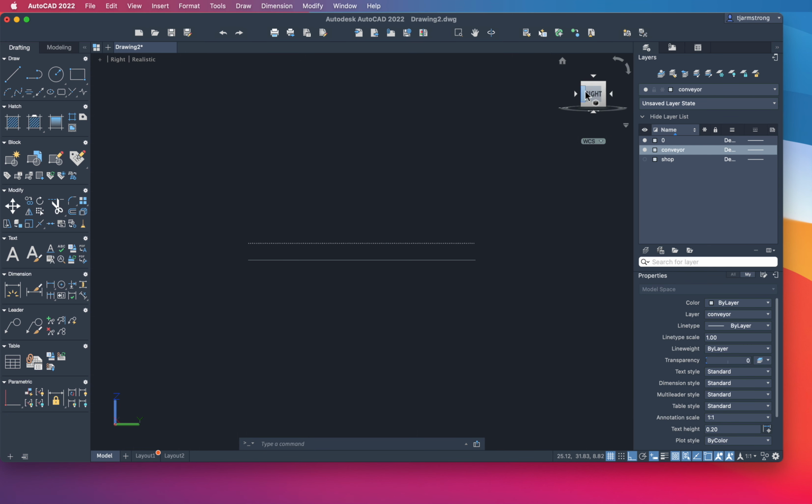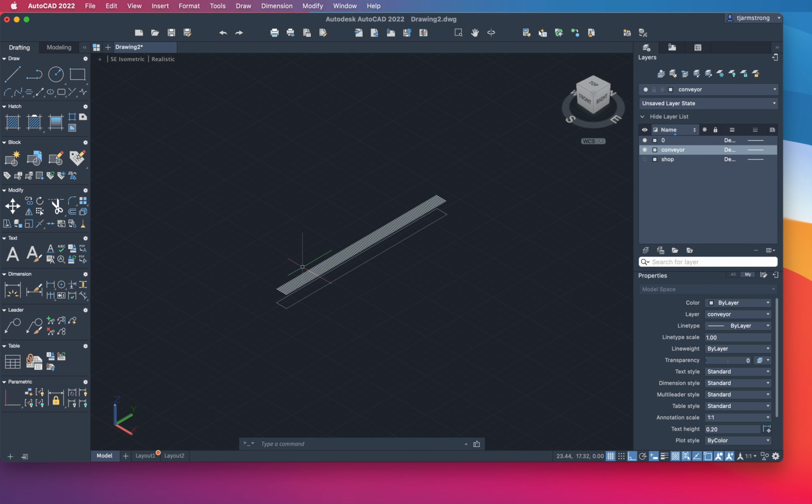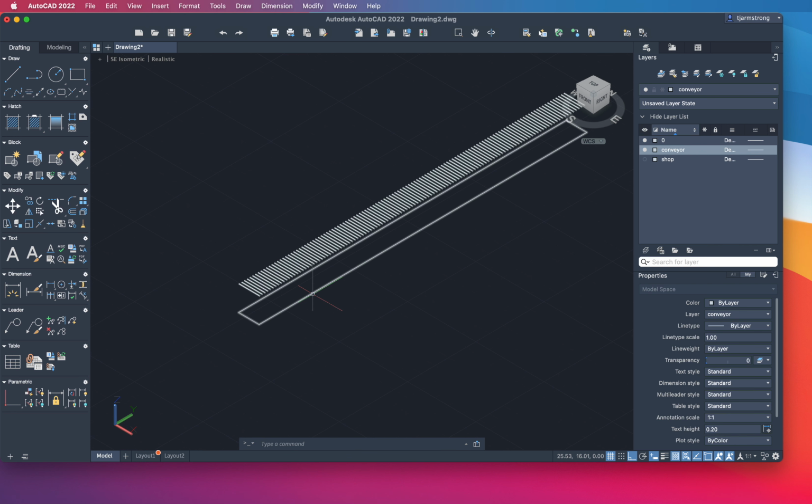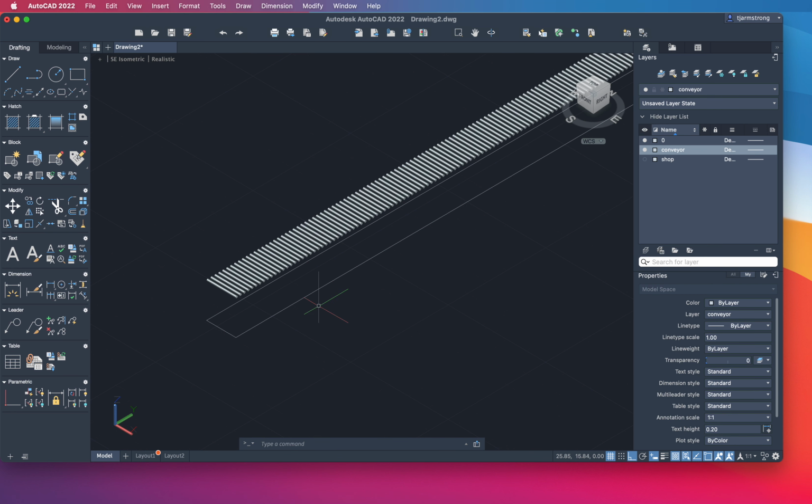That looks pretty good too. So come back here. So that looks good. The next thing we want to do is put some sheet metal around the sides of it. And the easiest way to do that is to just extrude this rectangle we used for the footprint up to the sides. Now we won't bring it quite all the way up to the top because we want our rollers exposed on top. So let's bring it up to say 0.875, so half the roller is exposed, and you could vary that depending upon what kind of mechanism you're using to support this.